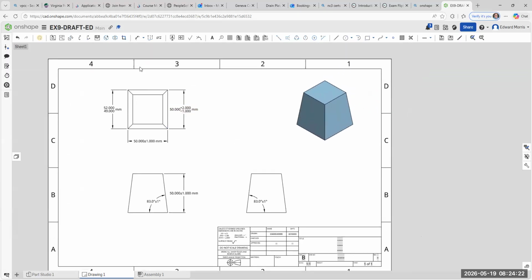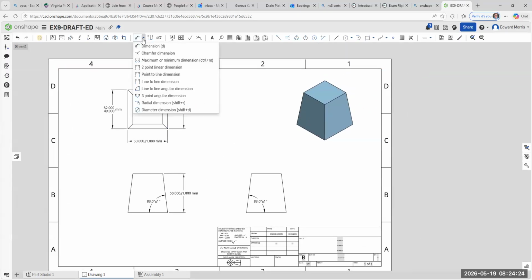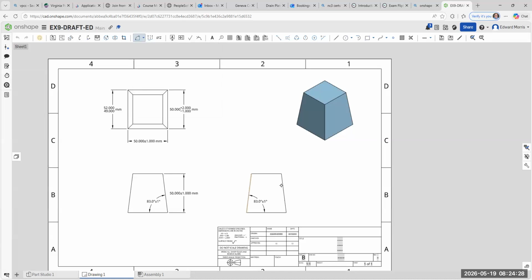You can also have an angular dimension. Look, you can have an angular dimension. See that? I'd rather not have the angle dimension on the part if you can keep from it. It's better to take the angle dimension off. I'm gonna put a dimension here. And if you can't see it, you can come up here and look at what I got.